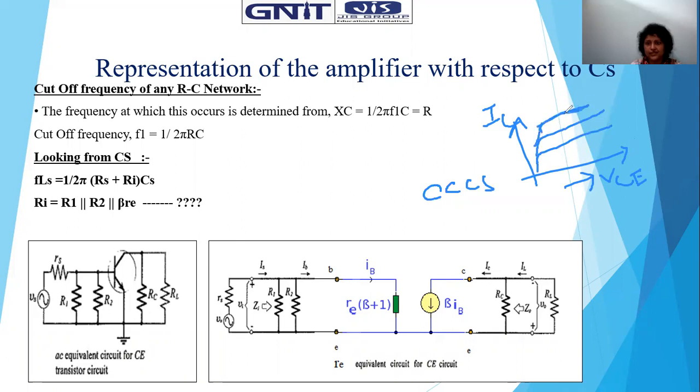This is the saturated current while the transistor is in the active mode of operation, for different levels of IB. So there is a dependency on IB, and that is why it is a current controlled current source: this is the input current and this is the output current. So IC is beta times IB, reflecting the current controlled current source representation of the transistor.